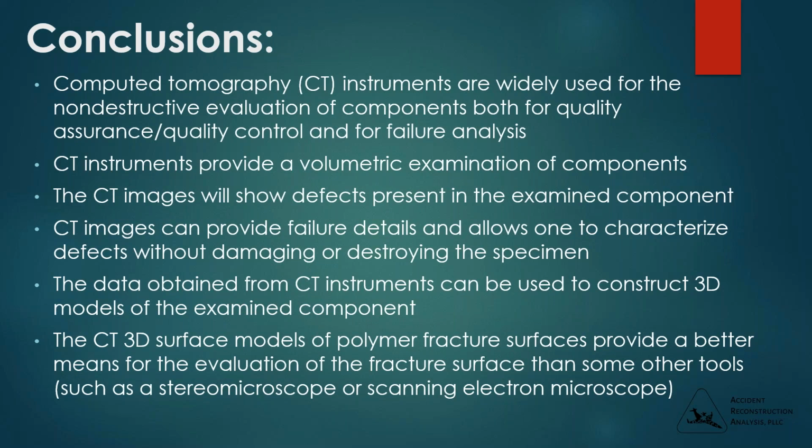CT images will show defects present in the examined components. CT images can provide failure details that allow one to characterize defects without damaging or destroying the specimen. The data obtained from CT instruments can be used to construct 3D models of the examined component. And the CT 3D volume surface models of polymer fracture surfaces provide a better means of evaluation of the fracture surface than some of the other tools, such as the stereo microscope or scanning electron microscope.